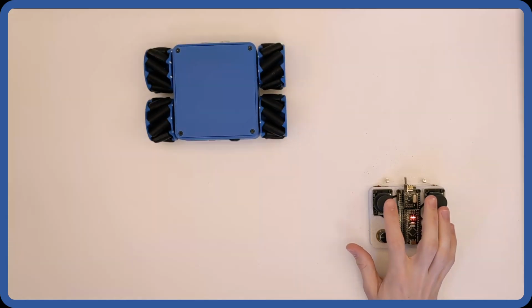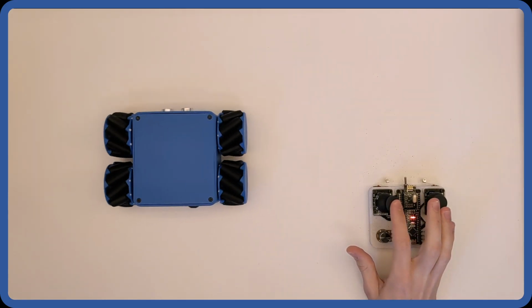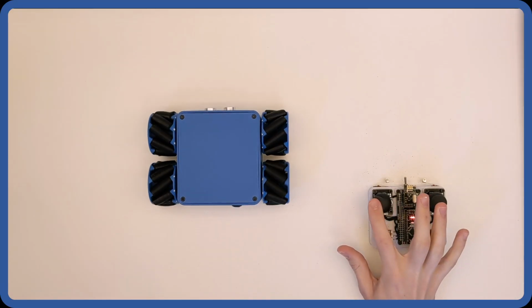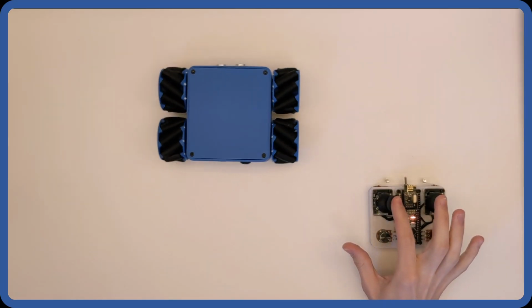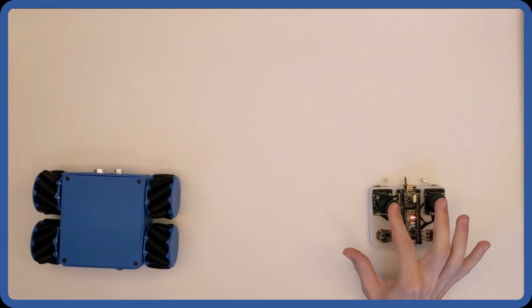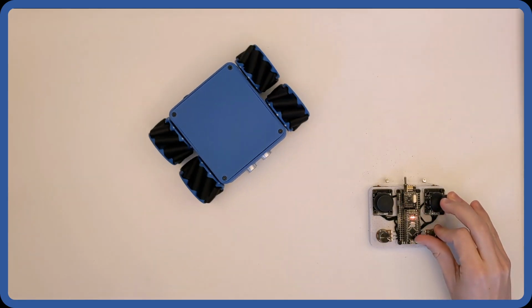As you can see, Newt has all the omnidirectional capabilities of my last robot with some distinct advantages. This design is more capable of going over bumps and through difficult terrains because all 4 wheels face the same direction and can be driven like traditional wheels. This comes with a caveat that the Mecanum wheels are more difficult to design and assemble than normal Omni wheels.